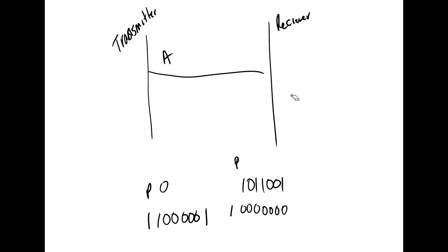then what would happen if one was set for even parity and one was set for odd parity? Yeah, well, it would transmit, but the receiver would always say not acknowledged, not acknowledged, not acknowledged, and it looked like the thing's not running, but your transmitter's constantly resending the same data.